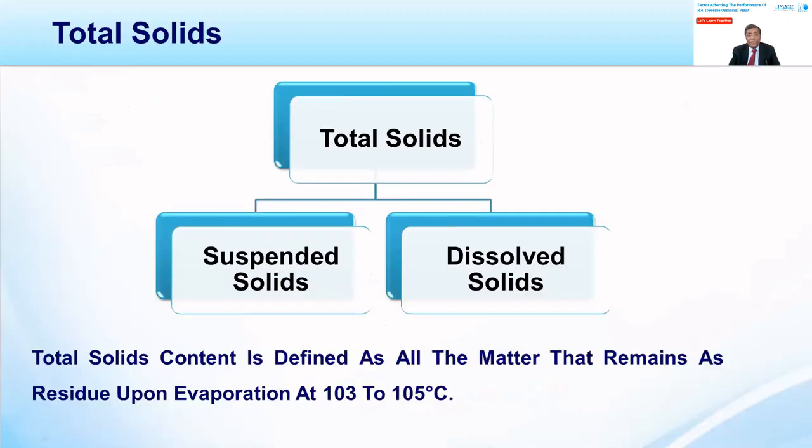The feed water, basically it is all a matter of pre-treatment: how we can have an efficient RO plant, a reliable RO plant, and how we can improve the efficiency and consistent performance, constant TDS and flow, and how we can maintain it. We have to design a very good pre-treatment to meet the feed water conditions as proposed by the membrane manufacturer.